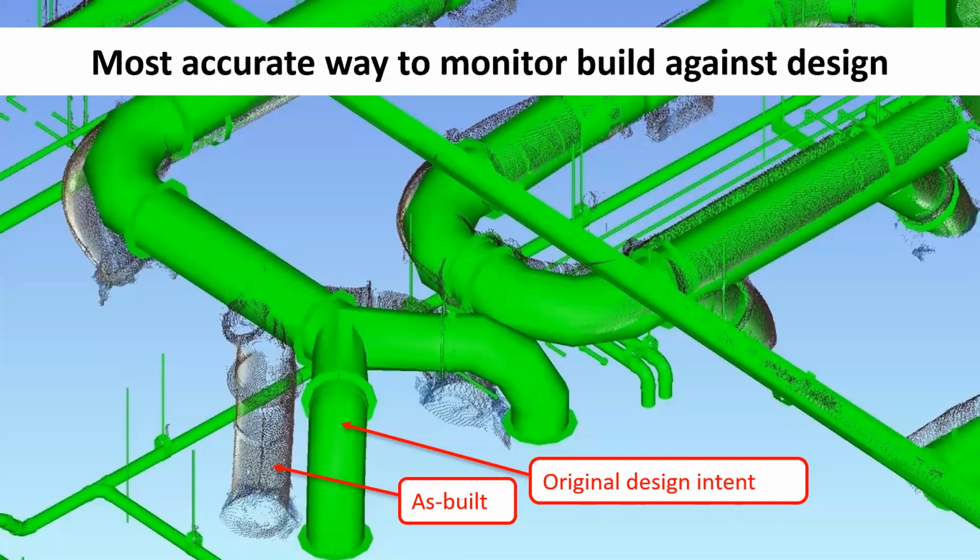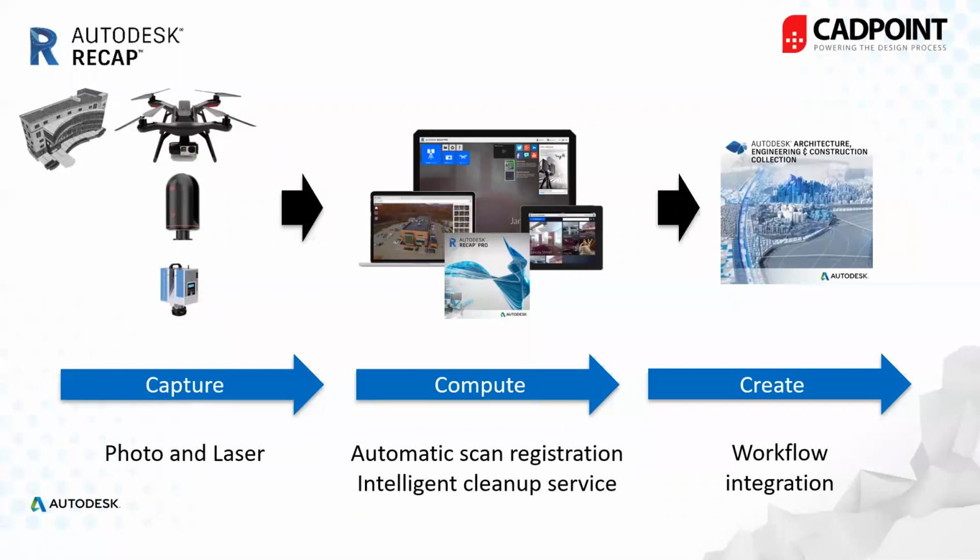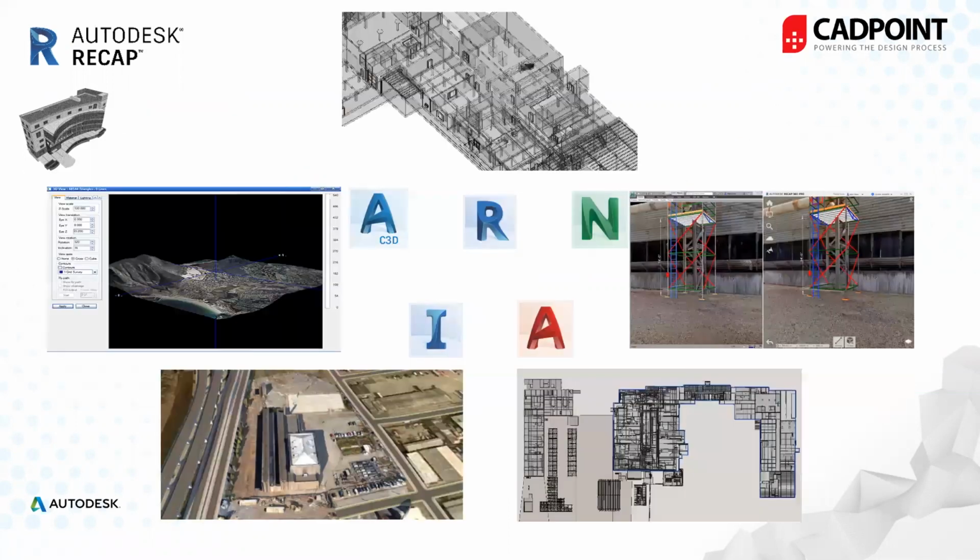either during the construction or after the project has finished as well. The process for doing that is simply capturing your data on site, whether with Faro or Leica equipment or a different type of laser supplier, or whether that's drone scanning or fixed tripods or equipment on site. That's then processed, or what's called registered, through Recap Pro. Then you can integrate that into other Autodesk workflows such as AutoCAD, InfraWorks, Revit, AutoCAD Civil 3D, and Navisworks. So there are a lot of integrations you can work with.